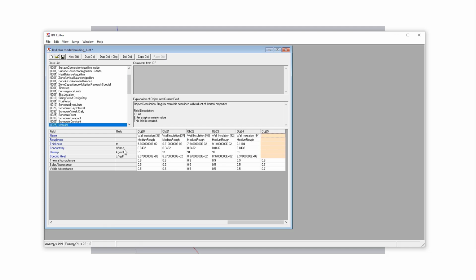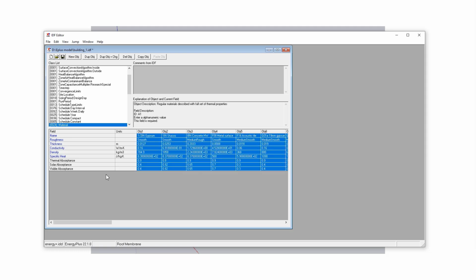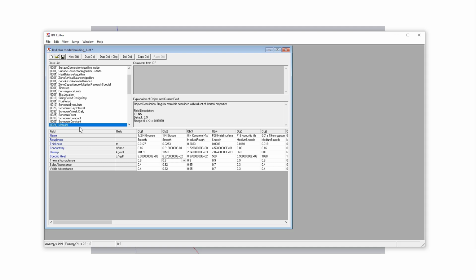The fields that are in blue color are the ones that you should actually specify. And if you don't address them, you'll get an error while doing the simulation. So if we want to assign a new material, you should fill all these blue colored fields, and there you will have a new material. So I just go on and delete this so I won't face any errors during the simulation. And these are actually, I think, fine for your goal, because if you want to assign new ones, you just have to search about them and fill these also.